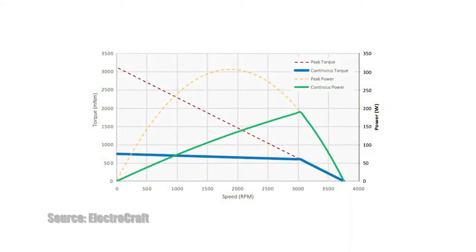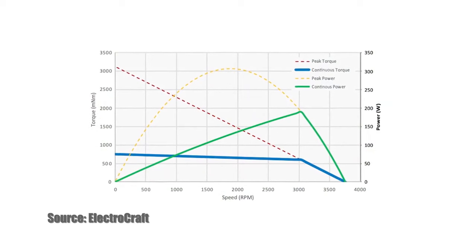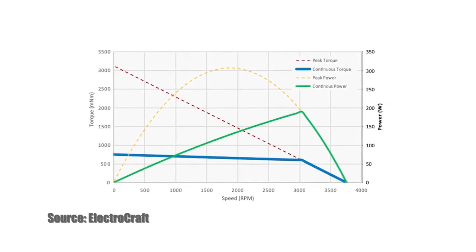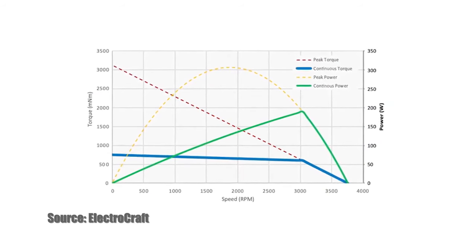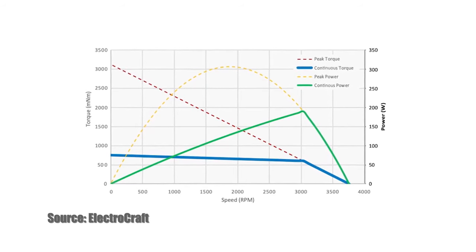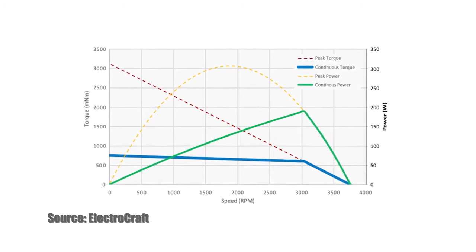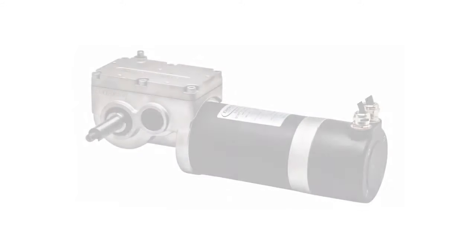For DC motors, the torque speed curve is relatively linear, so maximum output power occurs when the motor is operating at a point that corresponds to approximately 1/2 the stall torque and 1/2 the no-load speed.